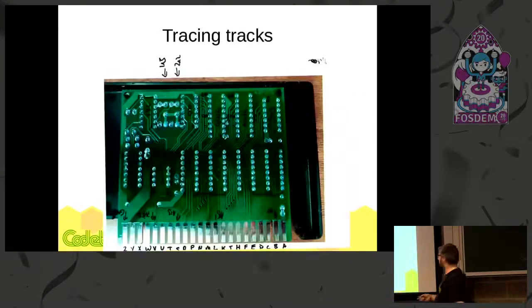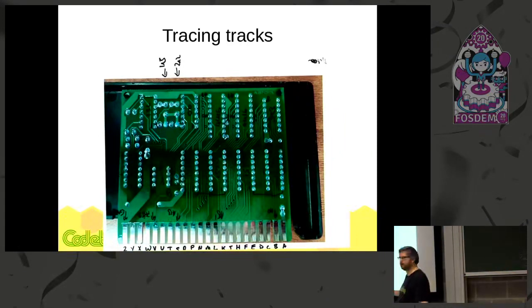So this is the underside of the board, and this is the next part of the technique of reverse engineering: I can flip it over and draw with marker on it saying what everything is, the edge connector, and actually work out definitely how it is all connected.